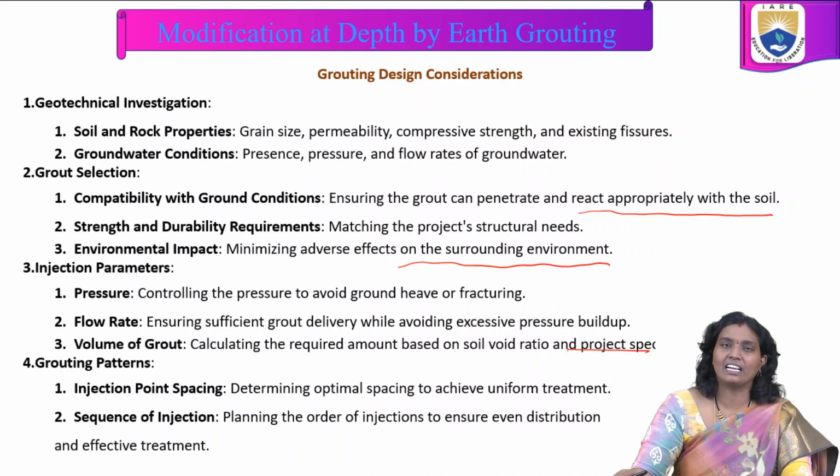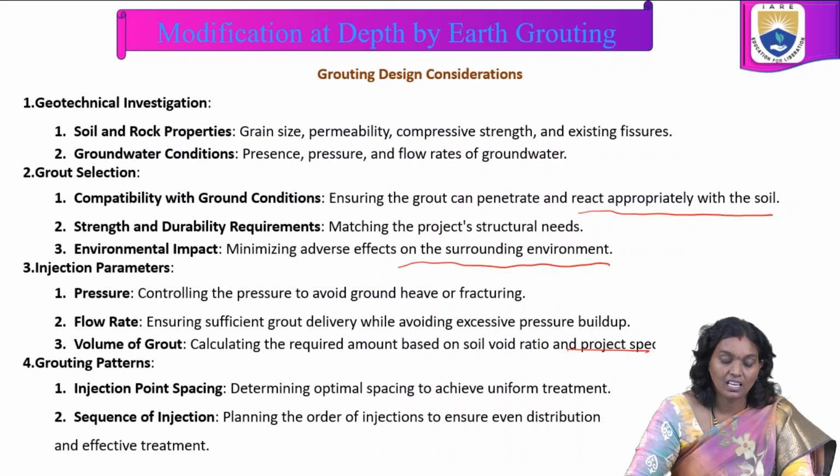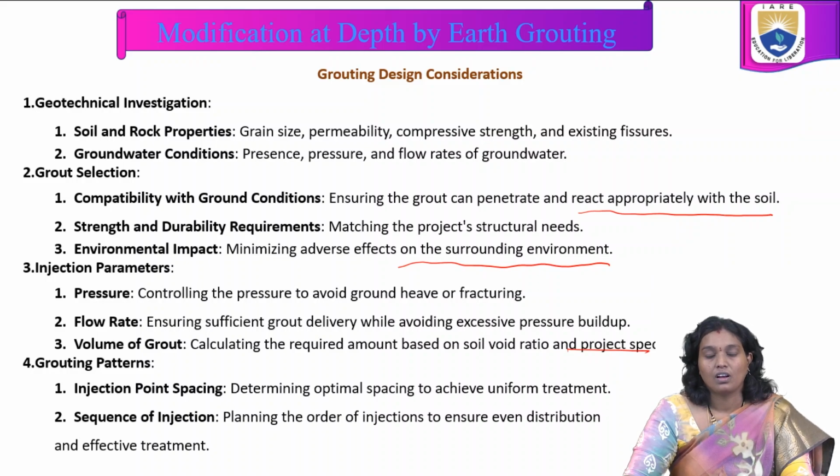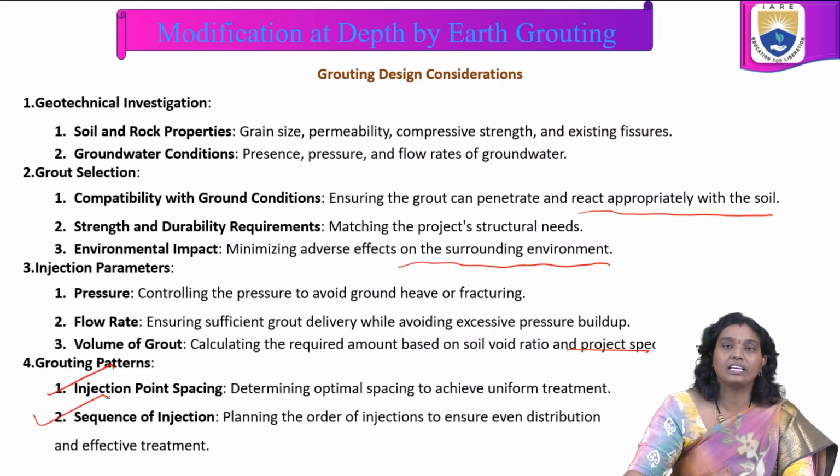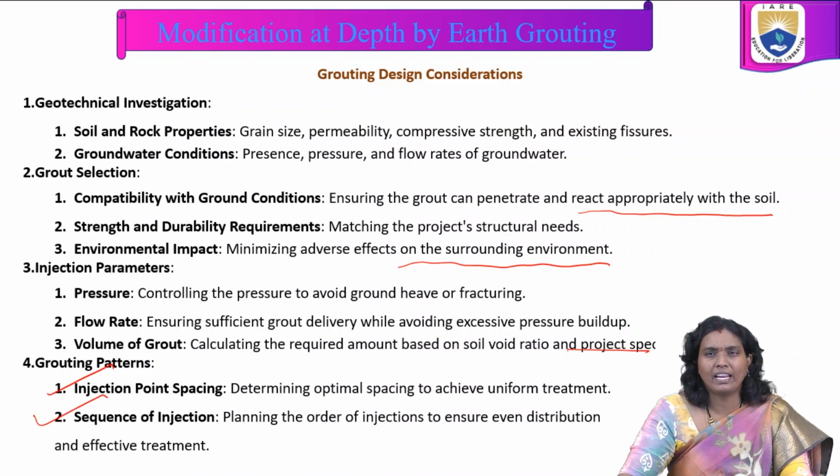The next design consideration is the grouting patterns. We have two different aspects here: injection point spacing and sequence of injection. Injection point spacing means determining optimal spacing to achieve uniform treatment. And sequence of injection means planning the order of injections to ensure even distribution and effective treatment.